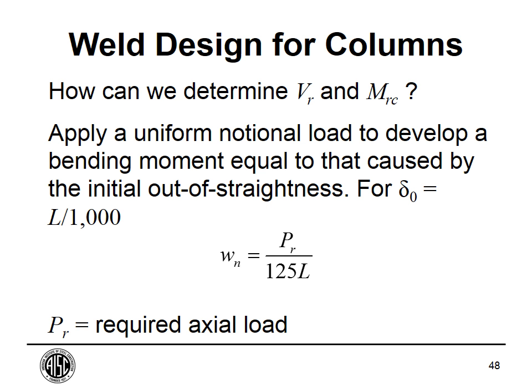Well, I'd mentioned one of the papers in the last presentation that you can look at. It was even in the references. But really, this is an easier way to do it, and it gives you a good procedure on how to calculate the shear and the moment at the theoretical cutoff location. What I did is I stole some information from the direct analysis method. You know, they've got all the notional loads, and for the method that's spelled out in the specification, you apply your notional load to account for any initial out of straightness or out of plumbness of the frame. And that's what we're going to do here.